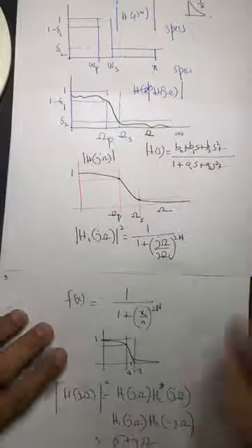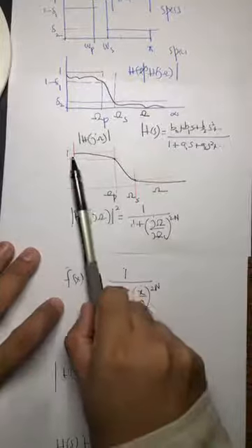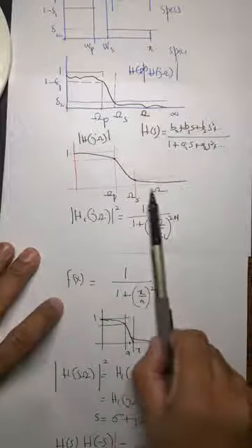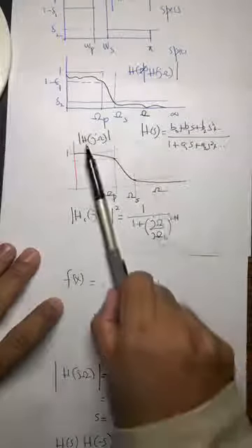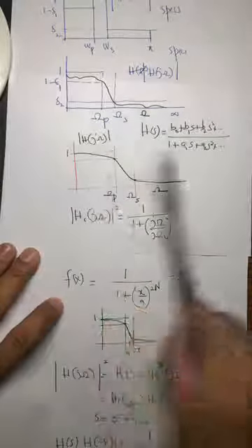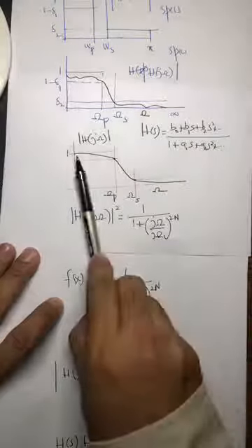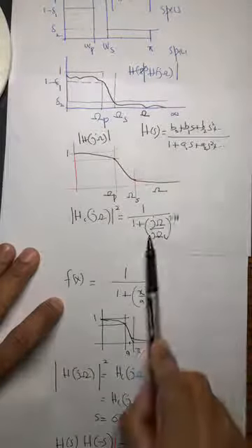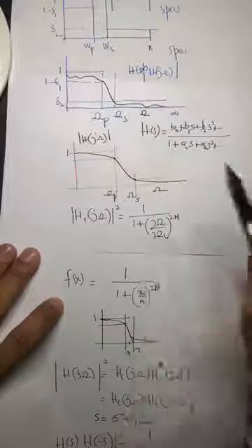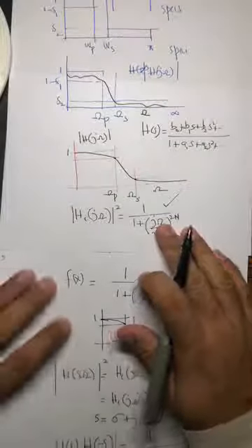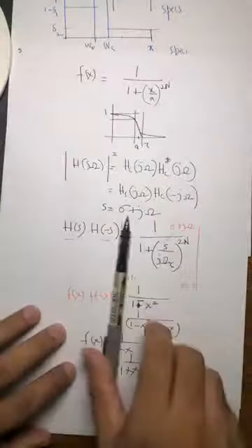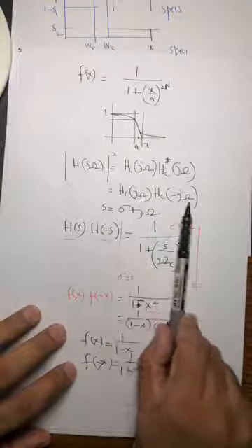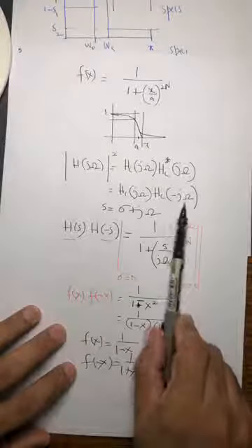Okay, let me just recap, because this is the genius of Butterworth, and he could figure out a graphical expression which could live in this area, which is the allowed area, not getting into the forbidden. So the rest is the forbidden area. It lives its life in this region, and it's a nice mathematical expression like this. So he said, wow, I now have a mathematical expression, but this is for magnitude square. The second one, what to do with the magnitude square? You said, yes, let's have magnitude this into its conjugate, and the conjugate is minus.